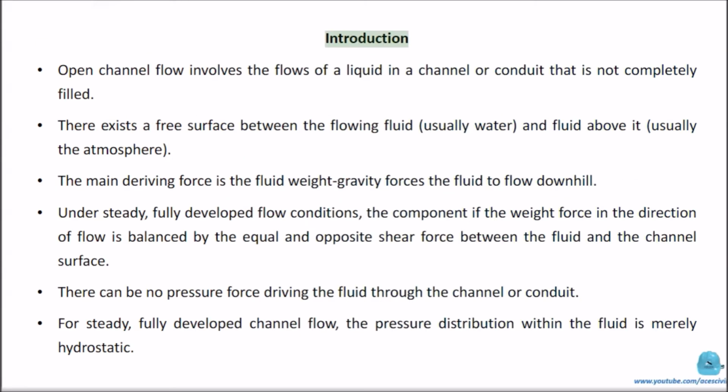Introduction. Open channel flow involves the flows of a liquid in a channel or conduit that is not completely filled. There exists a free surface between the flowing fluid, usually water, and fluid above it, usually the atmosphere. The main driving force is the fluid weight. Gravity forces the fluid to flow downhill.